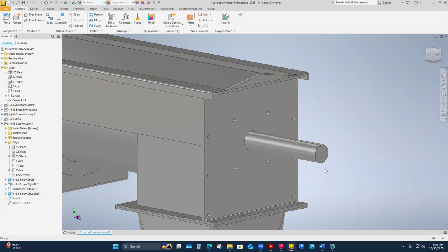Its data sheet said I needed to be under this kind of fit type or its tolerance. And then my machinist would need to know that to be able to turn this shaft down to fit my bearing. And so that is the kind of work that a mechanical drafter will have to research, work that's just a part of your regular everyday life. The engineer is going to sit there and crunch everything for you. They're going to say, hey, in our library, we have like the screw conveyor sizing sheets. Go ahead and dig through that, enjoy. So you'll sit there and look at that for hours and then start designing behind it.